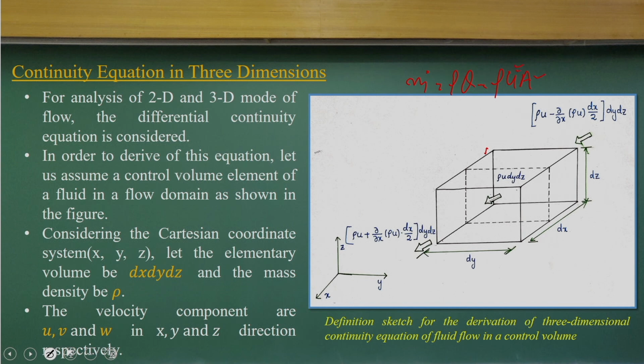So, the basic concept we are using is that the mass flux is equal to rho into q, and if I write in terms of velocity, I have rho, u and A, the surface area. So, I can compute the mass flux passing through a control surface as a function of density, the velocity scalar component and the area. That is a very basic thing.